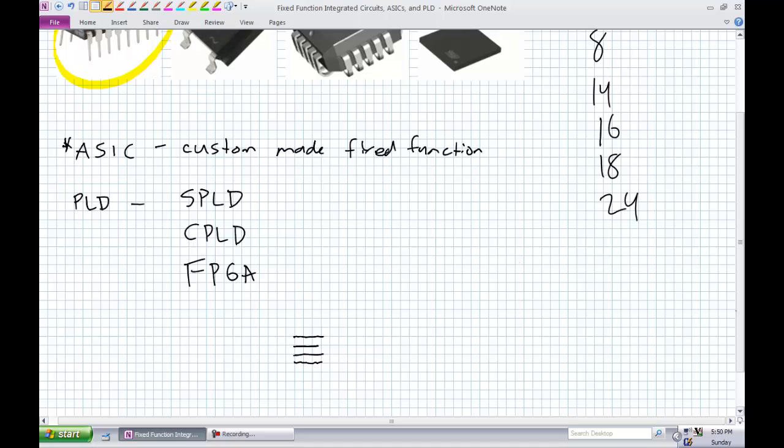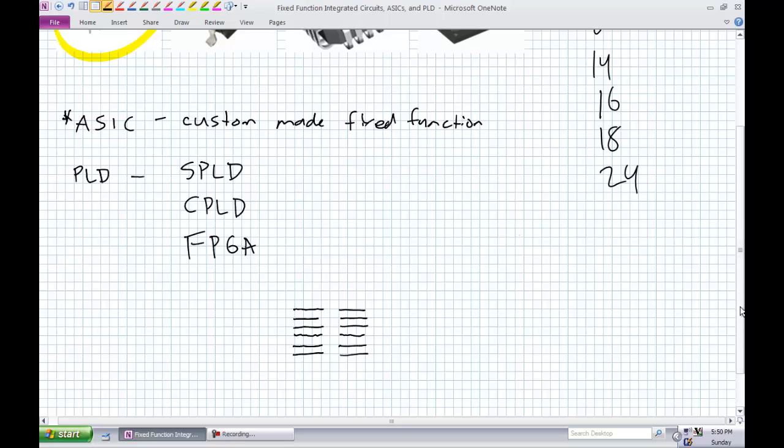Those rows in the protoboard are electrically connected. For the protoboards we use, it's 5 pins. That forms a node. Okay? Columns are not connected. So if I took a chip and placed it across one column to the next column, bridging those columns, because this might be an in for pin 1, and let's say in this particular case it is a 12 pin, so pin 1 is an in and pin 12 is an out.